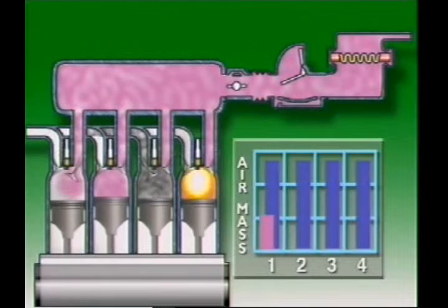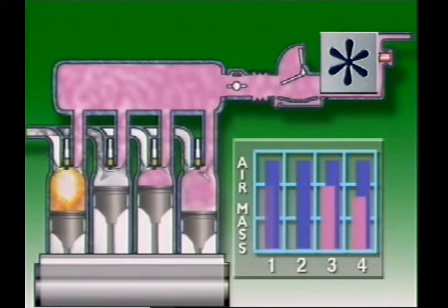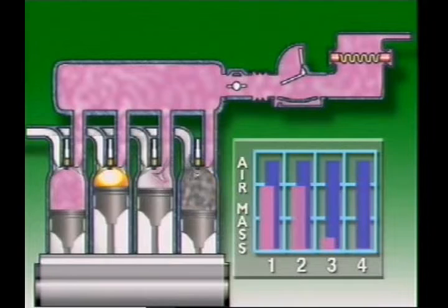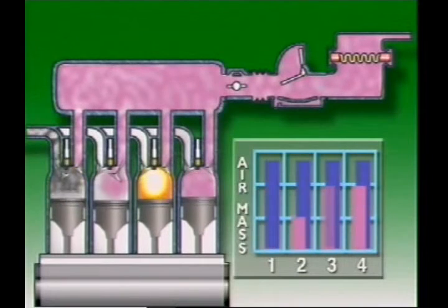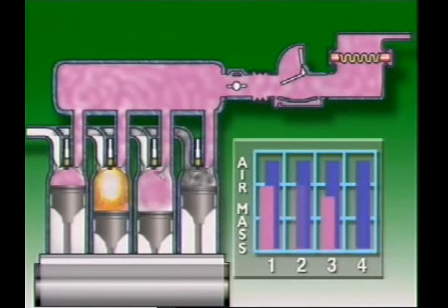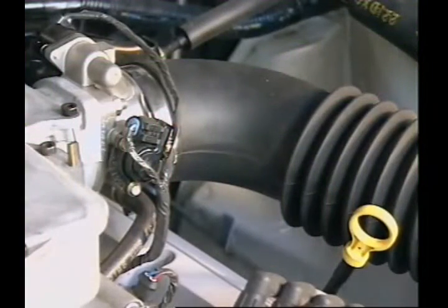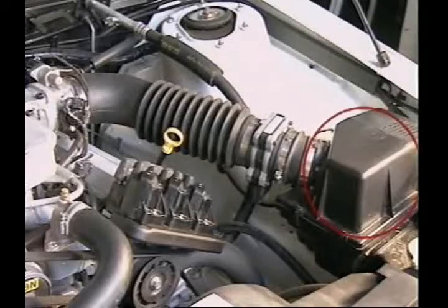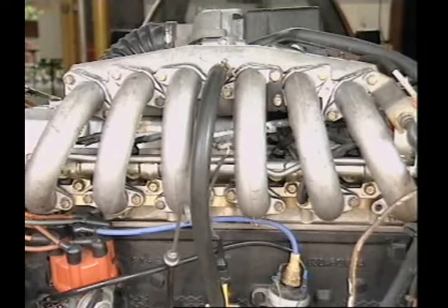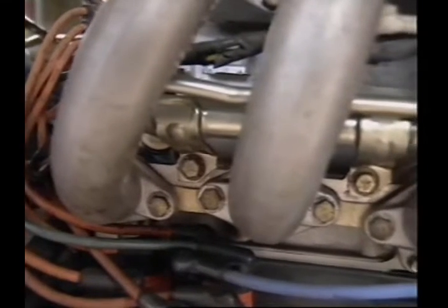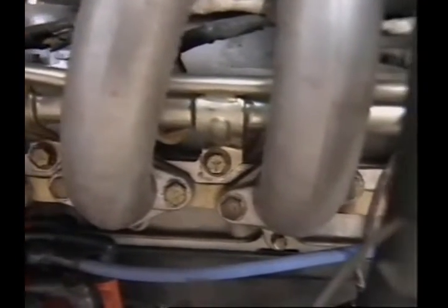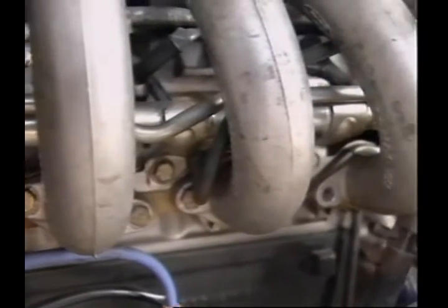The temperature of the air influences how dense the air-fuel mixture will be. Cold air is denser than hot air, so it has a greater mass in any given volume. This is why on most intake systems the air entry to the intake is away from engine heat, to ensure the entry of cool air. Since the manifold carries air only, it doesn't need to be heated by coolant. Filtered air arrives at the intake port as cold and dense as possible, ready for mixing with the fuel from the injector.